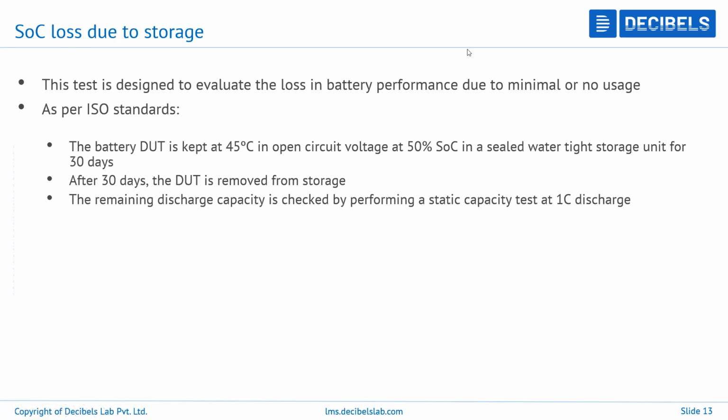So this test is simple. There is a storage chamber or a test chamber which is watertight and airtight. The cell is kept at exactly 50% state of charge, and it is stored at an ambient temperature of 45 degrees Celsius. It is disconnected from all the loads, again as per ISO standards, and it is stored in this chamber for a period of up to 30 days, minimum 30 days.